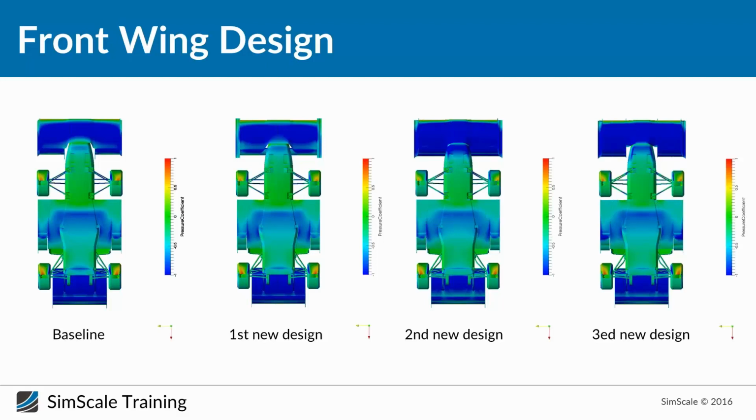Yeah, no, it's very interesting. I think these plots are showing quite well what's happening here. Obviously, we are missing the information of the balance of the aerodynamics as well, because the main attribute of the front wing is to change the aerodynamic balance, and I guess on this car you want something close to 50%, or you want a distributed aerodynamic downforce between the front and the rear of the car. Yeah, that's right. We have results about the balance later, in the last slide.